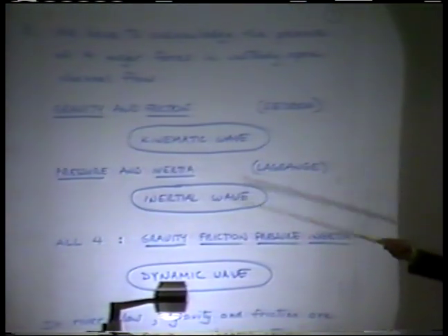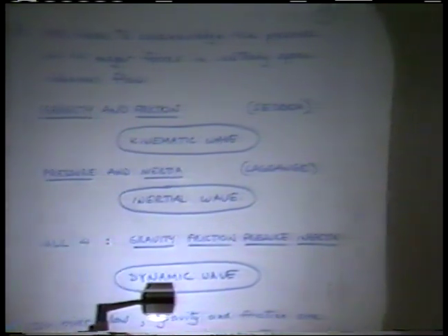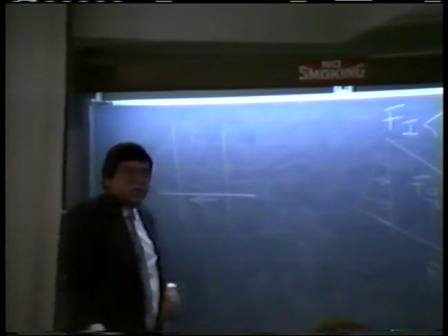if on the other hand you took the opposite side of the coin, you said, well, let me pose a condition in which the gravity and the friction don't matter. That would be kind of hard, wouldn't it? But I can tell you easily that the gravity is not going to matter if the channel bottom is flat. Right? There's not going to be a driving force in the direction of the motion. The component is going to be zero. The friction doesn't matter. Well, you can say we can now play God, right? Friction is there, out there. But if the reach is very short, the friction is going to be also very small compared to the disturbance. The disturbance is going to be big. The friction is going to be small. The gravity is going to be non-existent.